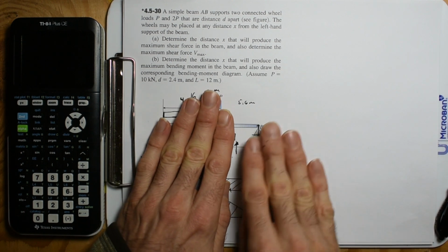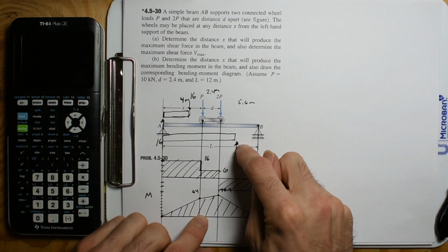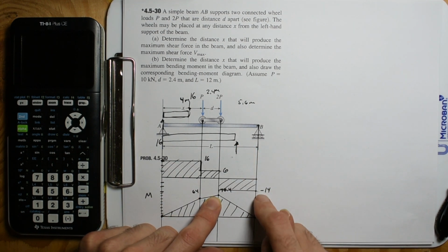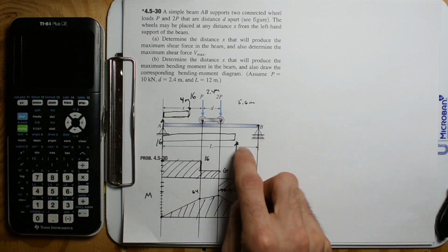Anytime you have something out here and you're driving an upward force on it, that's going to be a negative shear. I'll have to work on that, but that was the best I got. I think bending moment's way easier to figure out, but with shear you have a positive and a negative, and you're like, what does that mean?